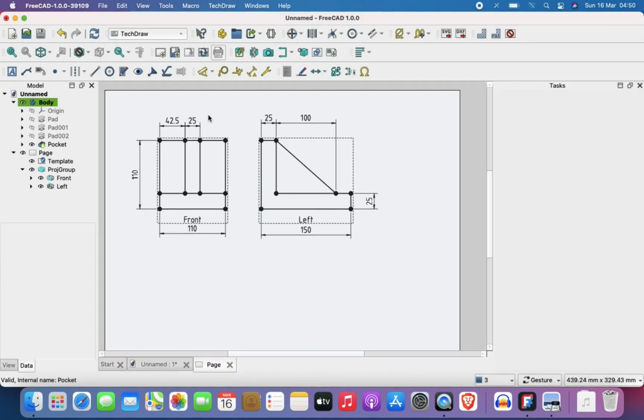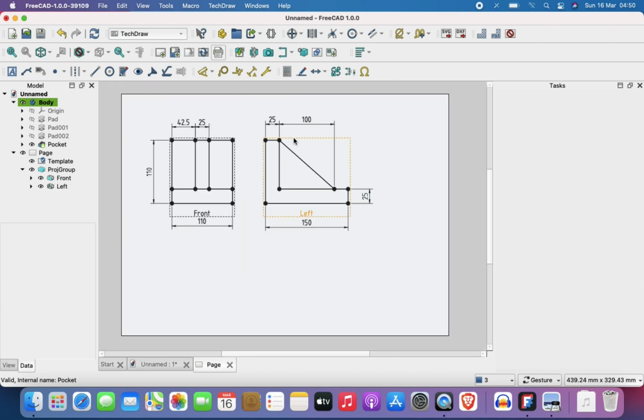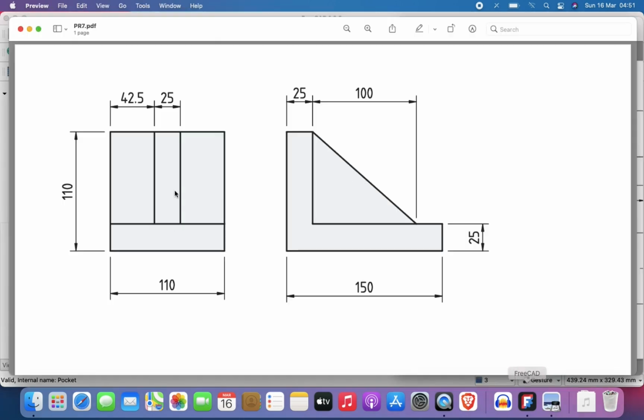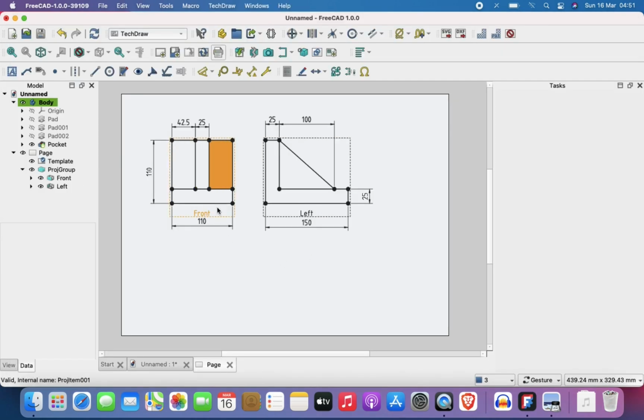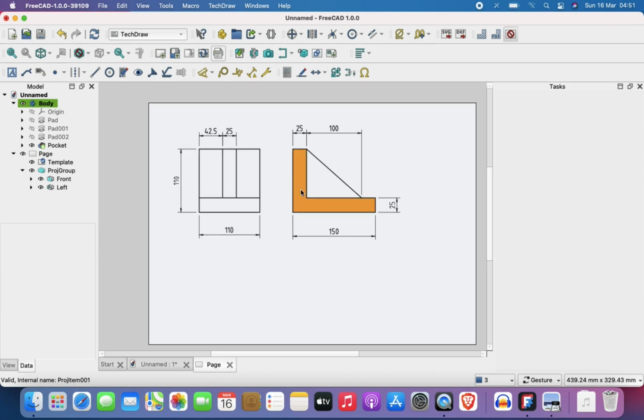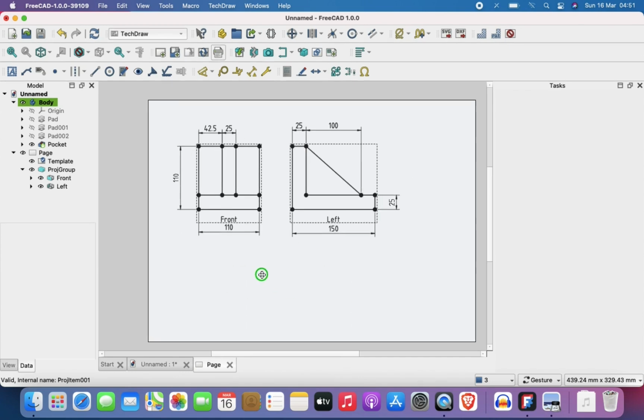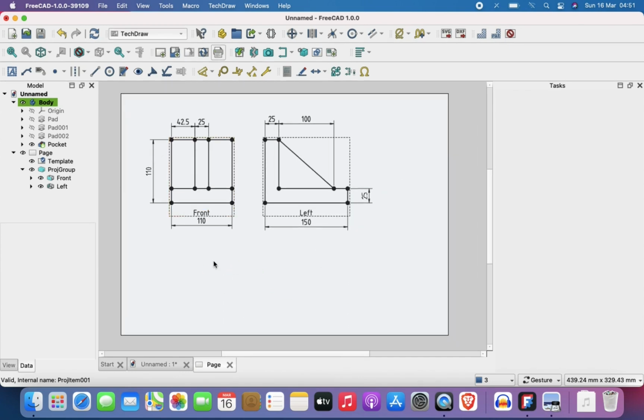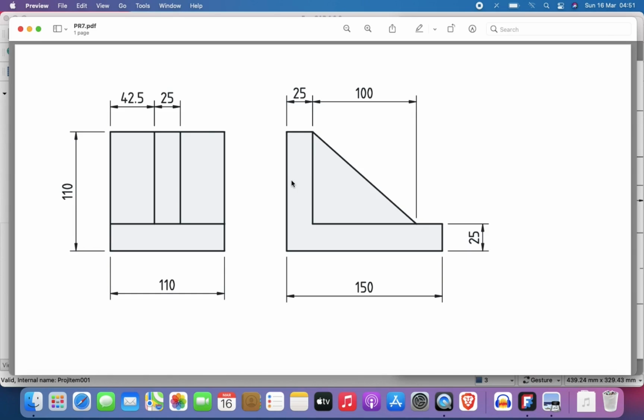For instance, let me go back to this. Before I go to that, you notice that we have some very thick vertices here, which are not showing up in my technical drawings, because those are for when you want to use it in FreeCAD. You can disable them as well, by right clicking and then doing toggle frame, so it shows you just the way your diagram will be exported, but it's helpful to keep that on while you are still working. So now I want to disable them, or rather, let me just go to the drawing.